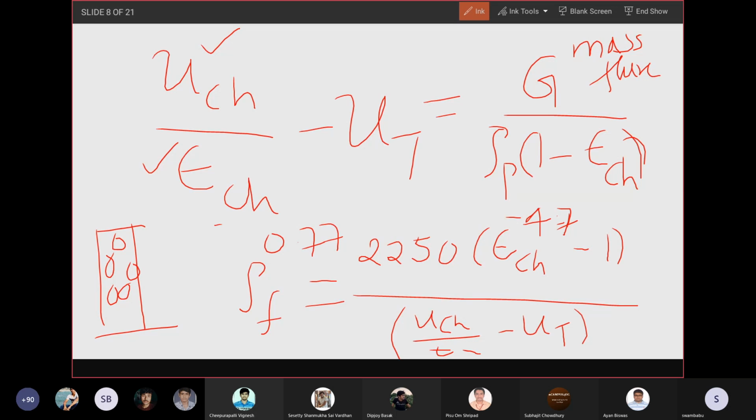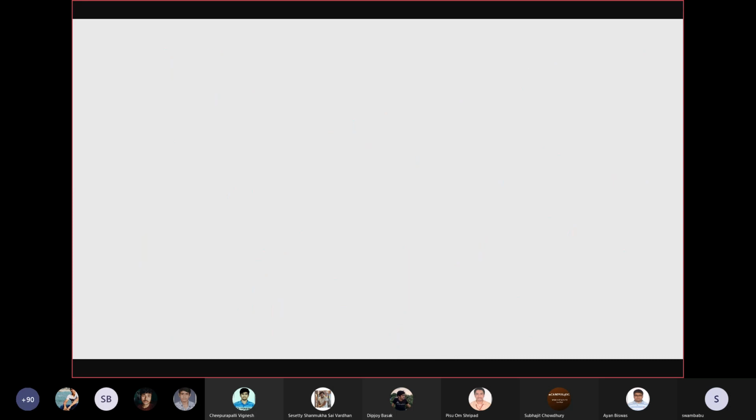Sorry, the equations are big and look awkward, but I will provide the book, and I can also prepare a PowerPoint to show in the next class. By solving these two equations simultaneously, we can find the choking velocity. Once you find it, the velocity of air in the horizontal or vertical section will be 1.5 times that.